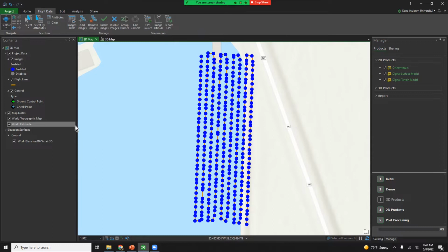And what that means is that I tell Drone2Map what the name of each camera is so that it'll generate 5 separate orthomosaics. This is not always necessary. I have processed my Altum imagery before without defining my cameras, but I have noticed that things work a lot better if I do this.